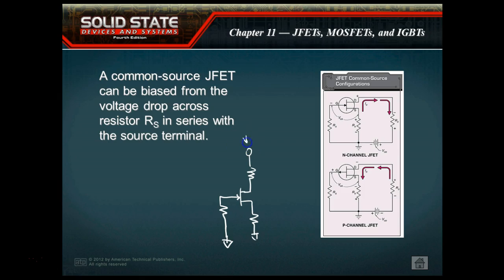And of course, this would be VDD. Now, this is VDD because this is the drain resistor. Generically, we refer to this as RD, and we refer to this as RS, and we refer to this as RG. Now, when you get out in the real circuits, these are going to be R1, R43s, R67s. It's just that we give these things a common name.